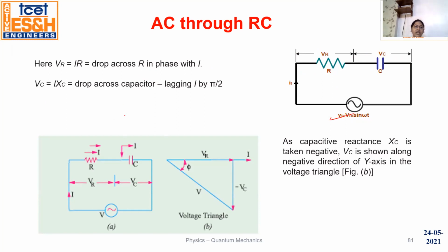And we know that in case of resistance, voltage and current both are in the same phase. Now in the case of capacitor, voltage is lagging and current is leading. So this is current and this is V. If V is the reference, then current is like this. So this is I. In case of capacitor, the phasor diagram follows like this.